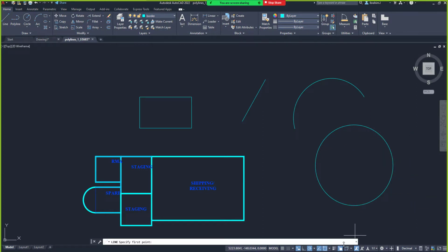But let me go ahead again, go to my object snap, and then activate center. Immediately I touch any part of my circle, what happened? Something comes up. What is that thing? Center. Is it making sense? And center applies not just to circle, it also applies to our arc and ellipse because they are all part of a circle, right? Whenever I touch my arc as well, I have a center showing, right?